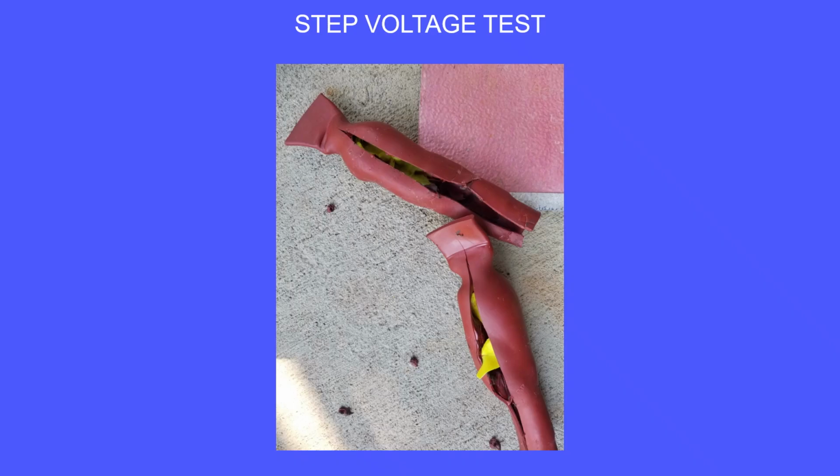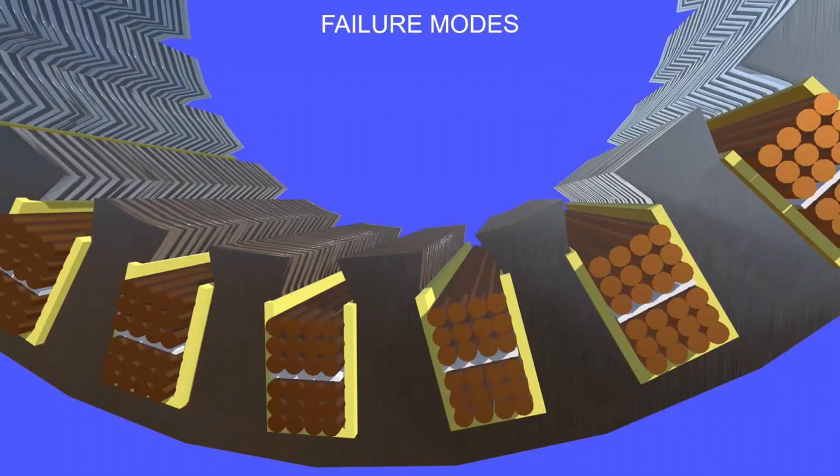The IR, PI, and step tests interrogate ground wall insulation. But we know windings fail between turns, coils and phases as well as to ground. Let's review the different failure modes that are possible within a motor winding. With each, ask yourself, can ground wall testing alone interrogate this type of failure? And can it allow us to identify the weakness prior to failure? Or do we need something else in our predictive program?